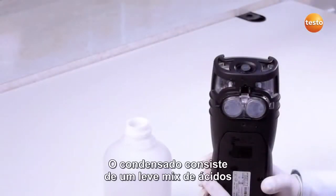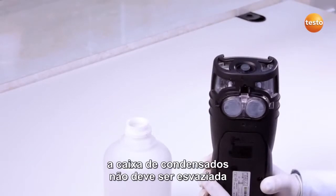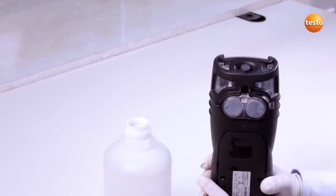As the condensate consists of a weak mix of acids, skin contact must be avoided when emptying. The condensate trap must not be emptied while the measuring gas pump is running.